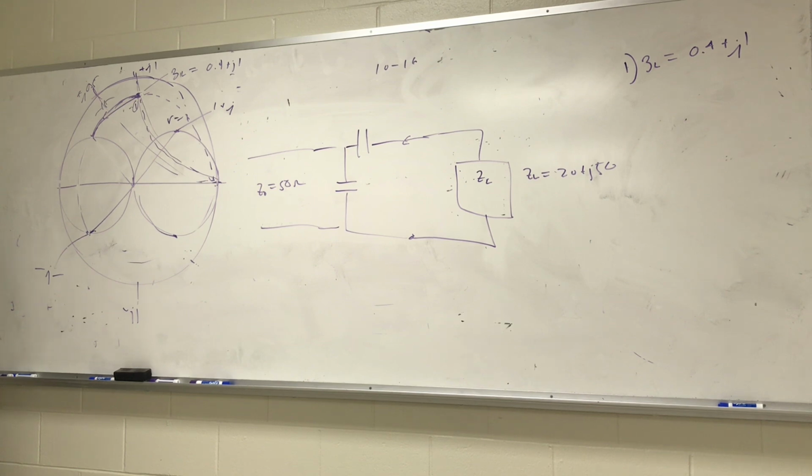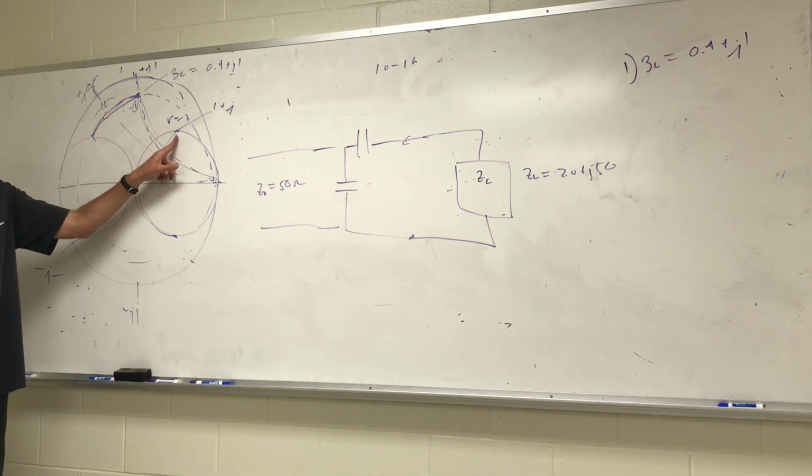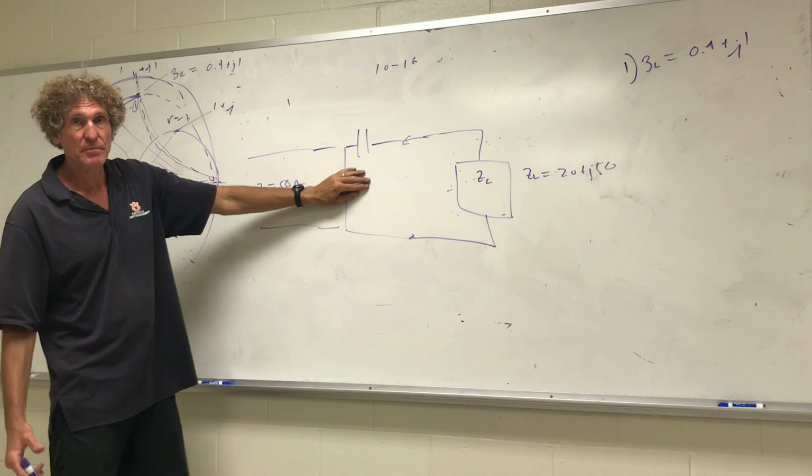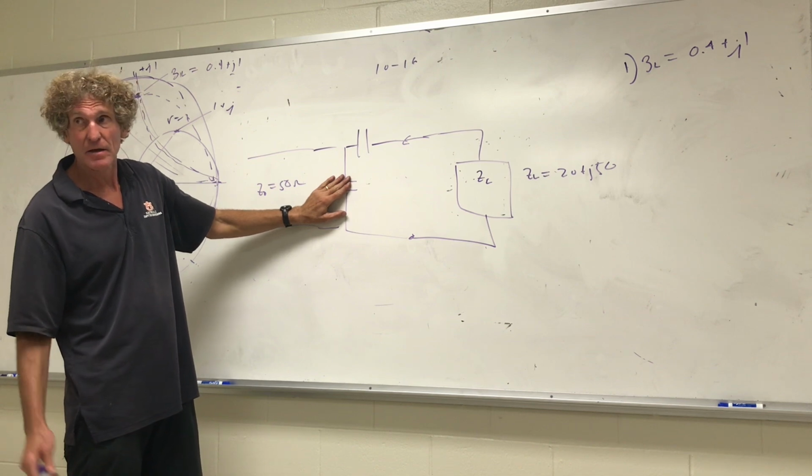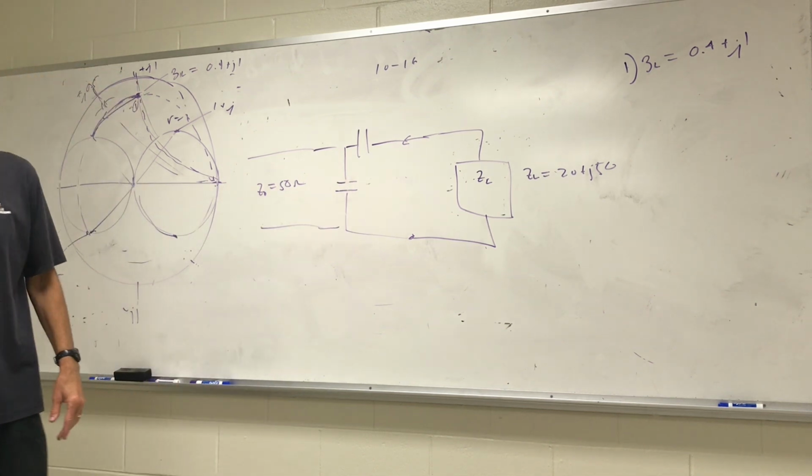Now, to answer his question fully, if I'm here, that's still impedance, right? Now I go up here, that is admittance, right? You see it's going to have a plus J component, right? In the admittance domain, we don't add a capacitor to that, do we? Because it would make it more positive. We add an inductor, minus J. So this would take it down there. So this would be replaced by an inductor. Follow the reasoning. You follow? You asked the question, do you see it or not?